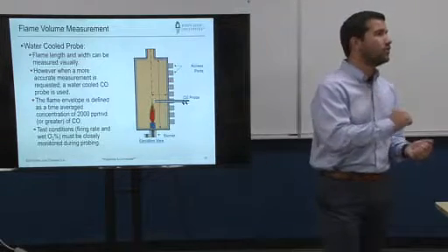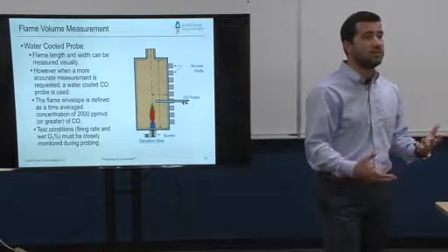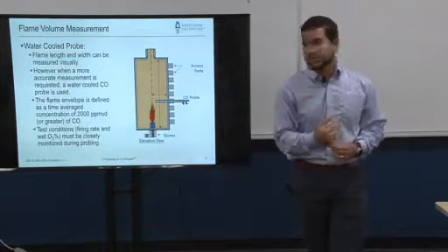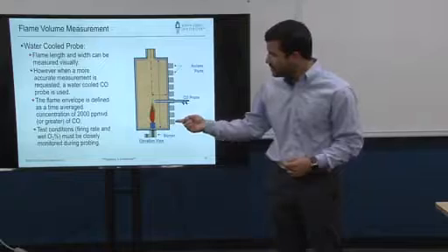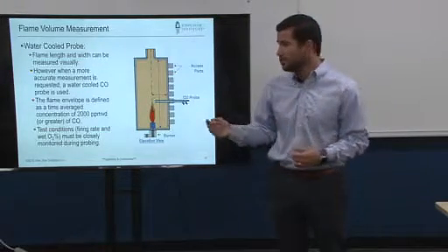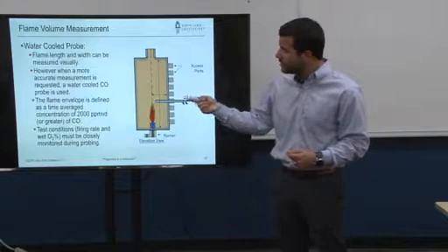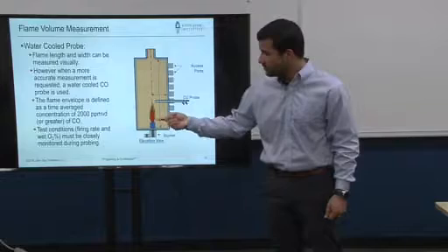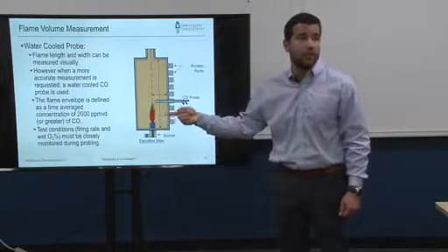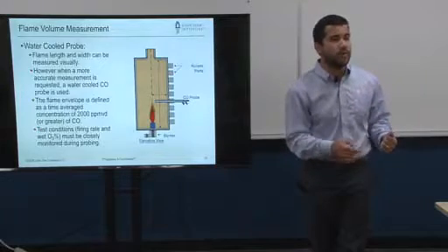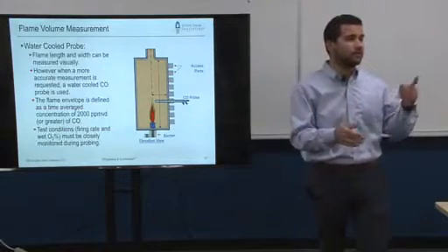So when you're measuring with the CO probe, if you measure 2,000 ppm or more, then you are in flame. If not, you're not in flame. So imagine just going through every single port. When you say you're going to do a CO profile, what you're really talking about is taking this probe and inserting it in every single port, and you're going to get as close as you can to the center line of the burner, and then you're going to pull back, say 6 inches, a foot, however much you deem appropriate, and then you make that profile.